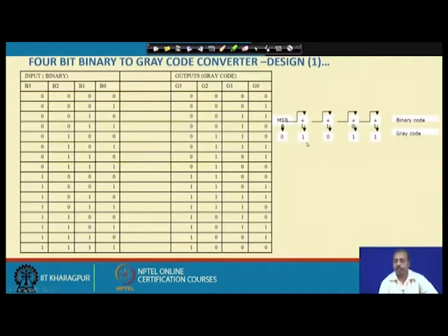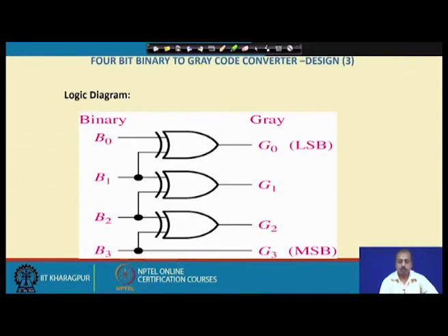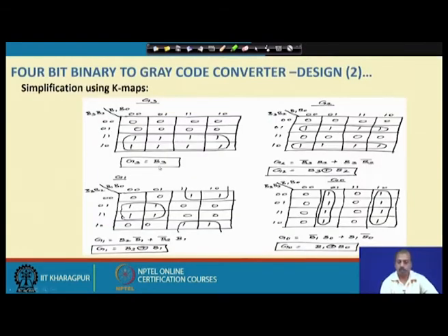You see that here also the basic definition of gray code is like that, and the corresponding Boolean function is also leading to the same thing. So, you can very easily draw a logic diagram which can convert a 4-bit binary code into gray code, where B3 will be directly copied to G3 as per this equation, G3 equal to B3.